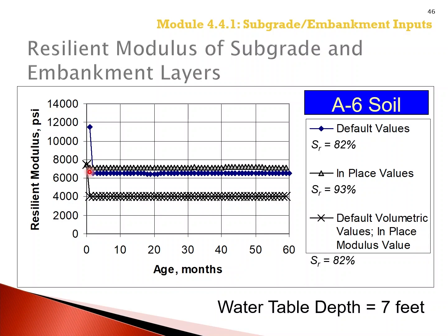In this case, the pavement ME program through the EICM only reduces the resilient modulus to a value of about 6,800 psi, which is very consistent with starting with the degree of saturation representing optimum condition, with the resilient modulus measured at optimum condition, and then reducing that value close to the degree of saturation from the CBR test.